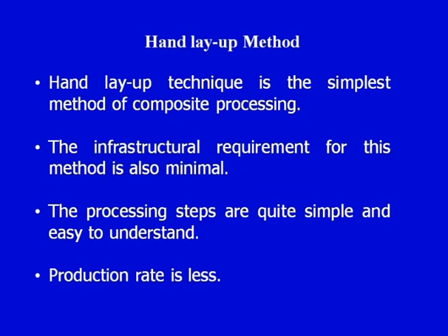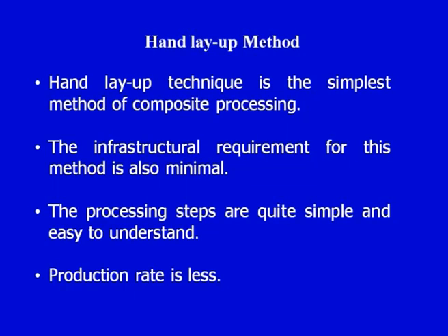The processing steps are quite simple and easy to understand. I can emphasize here that most of the research work that is being done in the field of polymer matrix composites, most of the researchers are using the simplest method of fabricating the composite materials, and hand layup is one of the processes which is widely used for making the composite materials, and more specifically the polymer matrix composite material. The production rate is less, it can be less to medium, and this particular process is quite suitable when the production volume required is minimum or to a medium level.